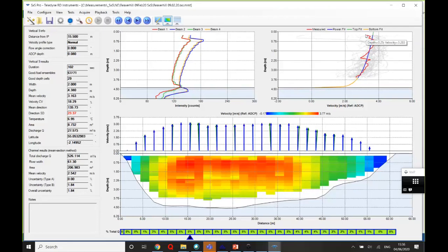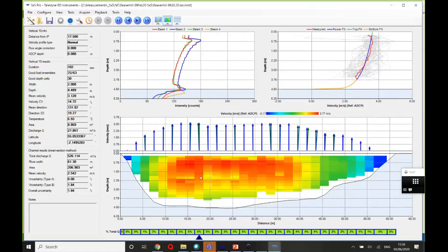So you can see in the velocity profile up here that what it's reporting is a water speed that's fast close to the surface, and then it gets slower, and then comes to a point, and then suddenly gets faster again. And it seems to do that at a number of locations. I mean, there was a lot of debris reflection. Yeah, it looks like it. You think that's an acoustic thing, an echo coming off the bottom? It could be. I'm not saying it is, but just knowing some of the problems we've had, it looks like that could be a bed reflection.